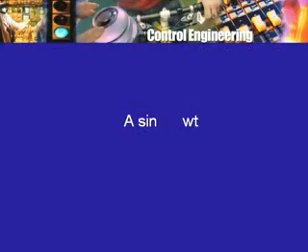So once again, just as 3000 rpm corresponded to 50 hertz, 1500 rpm will correspond to 25 hertz. So 25 into 60 is 1500, that is how 25 hertz. Remember the expression for the sinusoidal voltage that I wrote down earlier, it had something like A for amplitude into sine omega t, where this omega is called the angular frequency for the power supply voltage, and it of course as you can see corresponds to some turbine rotating somewhere.